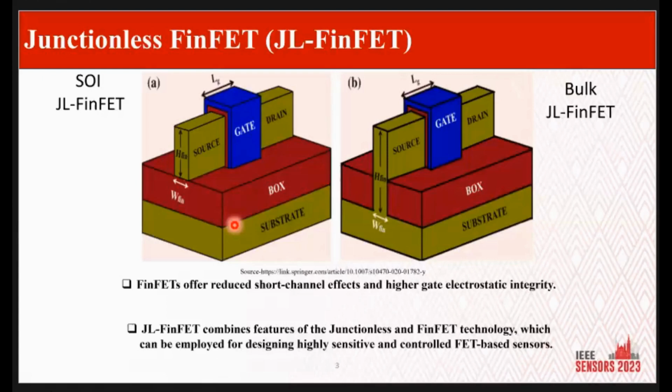One flavor of these devices is called the FinFET. I hope the guys online can hear as well. The FinFET device is basically a fin, and it looks like this. You have a source and a drain and a gate, and it has 2 flavors. One is called silicon-on-insulator. Basically, you have it on the surface of a silicon box. The other one looks like this. It's called bulk. It was introduced by Intel in 2014 to make it better and keep Moore's law going.